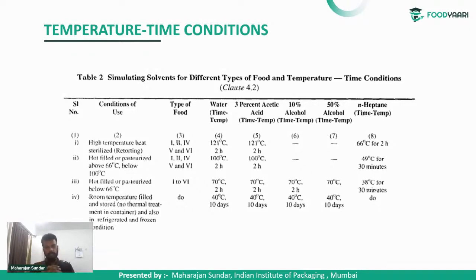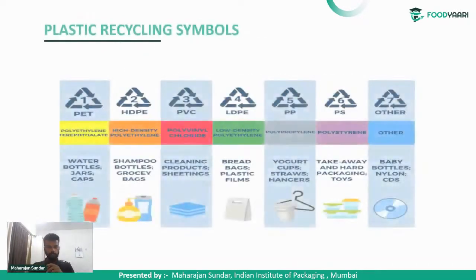For rigid plastics, the technique will be totally different, but the terms and conditions are same. What we will do is we will cut the plastic into pieces and we will put it into a simulant holding container, and same process will be followed. Then the plastic pieces of the bottle will be taken out and it is extracted, and the final value will be found out. And maximum for a rigid plastic, the value should be less than or equal to 60 milligram per liter.